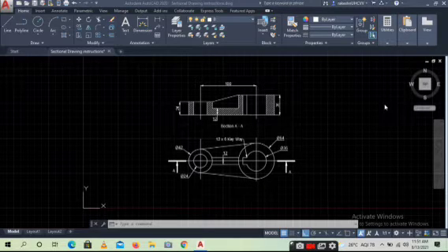Then once you finish the object line, if you are going to introduce the center line, you create a layer as center line and incorporate the center line in that layer, and then the dimension, like that. So simultaneously, along with the drawing, you can add each component in that particular layer.